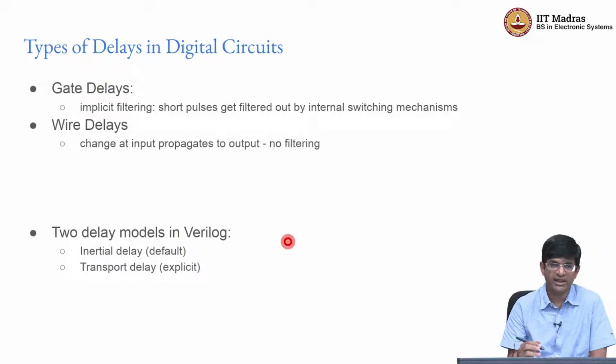But one very important caveat that I want to give over here is you need to be very careful with how you use these. In practice, it is actually quite rare to use many of the different modeling techniques that are present in Verilog, right? And you would usually be using only extremely simple forms of the models. Why is that? Because as I told you, having complicated delay models in your Verilog code does not actually imply that those complicated models get reflected in hardware. It's usually the other way around.